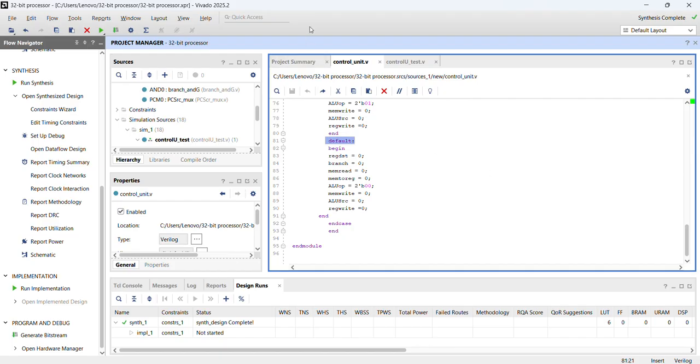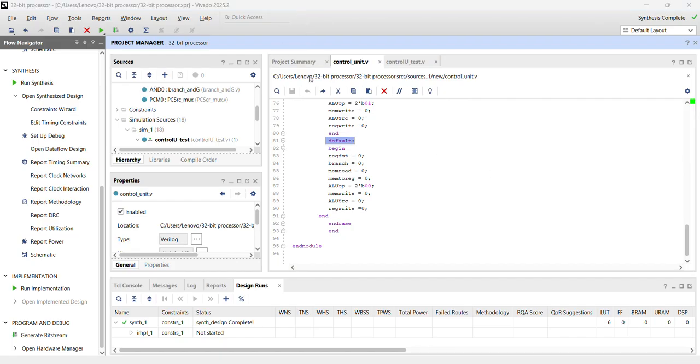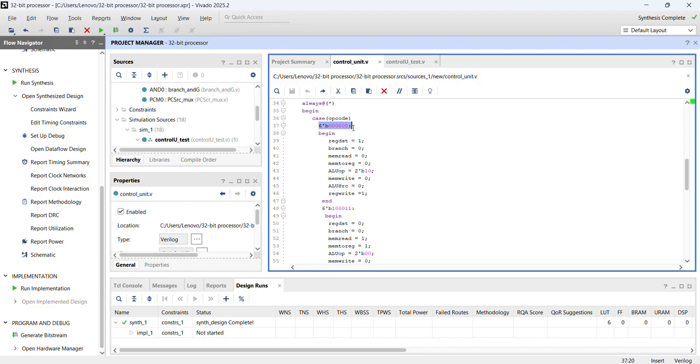These are not random four cases, because in this way we check the ALU operation or control unit operation. So, for example, in our first case we assigned the opcode as 0 0 0, so the control unit will understand that this is the R type instruction. Then it will generate a specific combination of the control signals so that the ALU performs the required operation, and the result will be written back into the register.